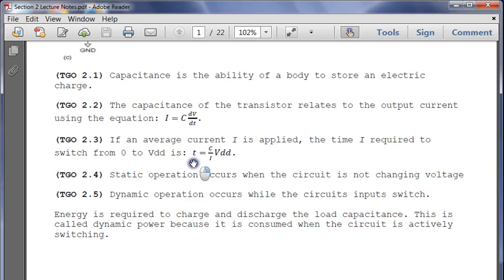Now, if you're trying to regulate power consumption, remember our basic equation is V equals IR. If you burn it up really fast, guess what? You're consuming a lot of power. And power consumption is something we have to be really concerned about. We want our laptops to work a certain amount of time. We want our phones to work a certain amount of time. High frequency is great, but it's a trade-off. And what we're going to learn is that frequency is directly proportional to power consumption.